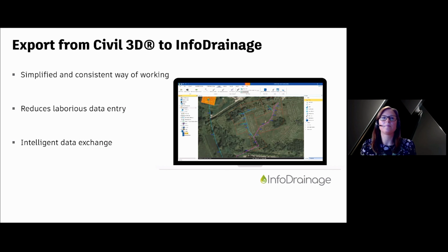Here we get to see the benefits of the accurate layout of those stormwater controls or green infrastructure elements. You can see in the visual representation of the design in the 3D orbit that not only are the stormwater controls themselves laid out accurately, but the location of the inlets and outlets and therefore the correct connection locations have been maintained. We can also make design updates.